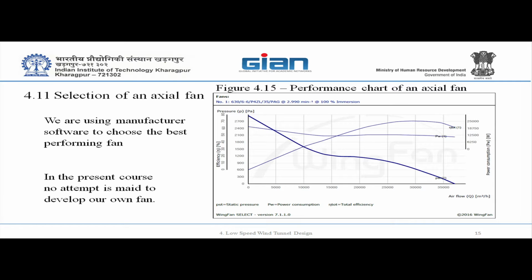This borderline is intersecting at zero static pressure. Tell me, what is that indicating? This indicates that your fan is free, not connected to anything, just the fan. Both sides have atmospheric pressure. That's it. This is the performance of the fan.